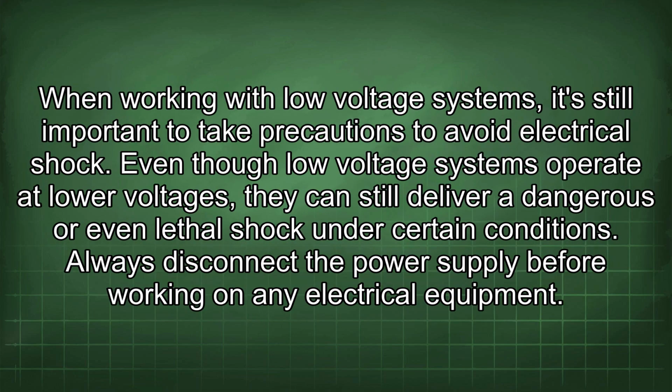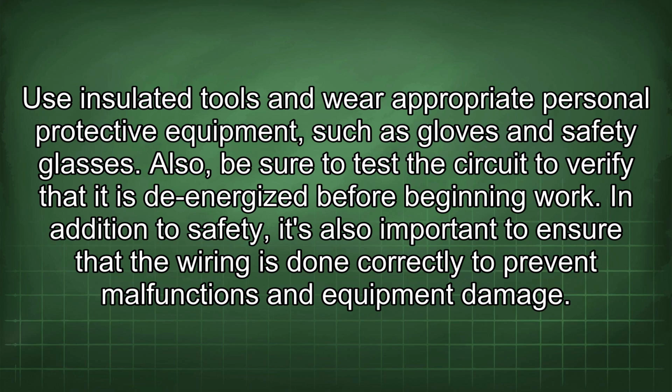When working with low-voltage systems, it's still important to take precautions to avoid electrical shock. Even though low-voltage systems operate at lower voltages, they can still deliver dangerous or even lethal shock under certain conditions. Always disconnect the power supply before working on any electrical equipment. Use insulated tools and wear appropriate personal protective equipment such as gloves and safety glasses. Also, be sure to test the circuit to verify that it is de-energized before beginning work.